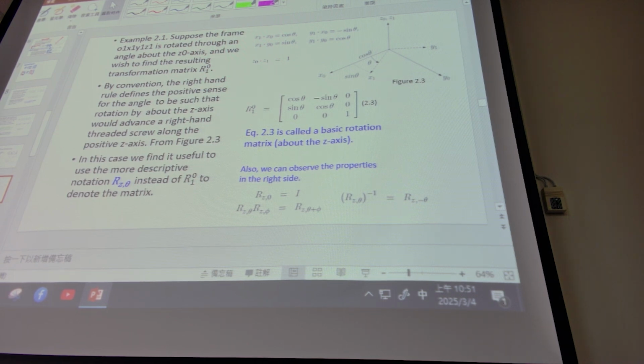Okay, you can rotate it with the z-axis in this case. In the z-axis, you can see from frame 0 to frame 1 we maintain the z-axis, it rotates by itself. So only the x and y-axis rotate with a specific angle theta. So the previous three-dimensional rotation matrix reduces to this type,